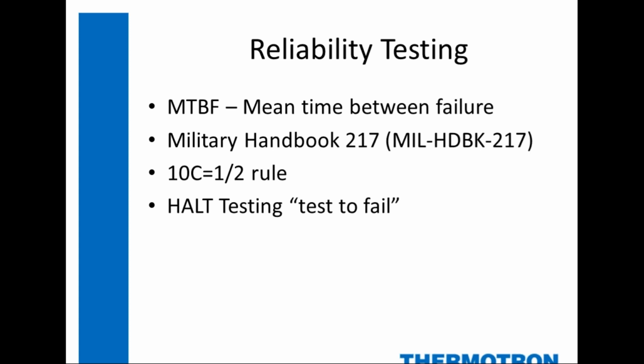So you can kind of flip that around and say, okay, if we do a test at 80 degrees C for 30 days or 60 days, here's the predicted life that we can expect out of it or calculate based on that test. So reliability engineering, it's obviously complicated. That's just a real basic example.